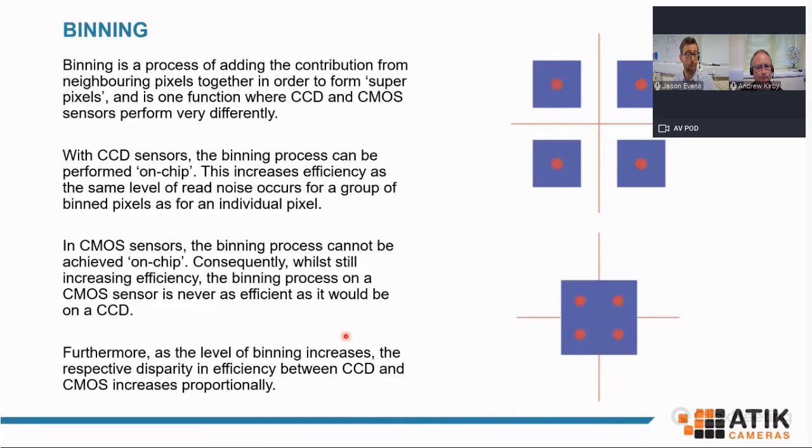So when imaging, a key parameter is often going to be the signal to noise ratio. In essence, do you have more signal than you have noise generated in your system? If not, you'd struggle to differentiate between the two sources and you won't get a particularly useful image, or certainly you'll get something where you can't really tell what's on the image. In general, you're going to want a signal to noise ratio in excess of 2.73 to start getting some more meaningful pictures.